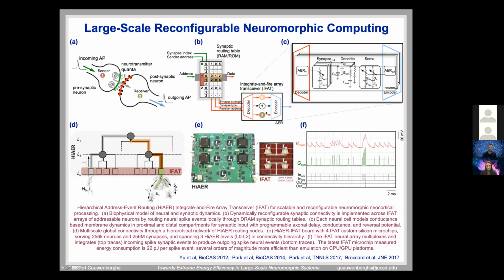So HiAER stands for this hierarchical organization, where we have a tree of nodes in the network where we just do message passing from one level to the next level. And so you only communicate source addresses rather than sending all the events, right? At the leaf node architecture, you have those efficient processors that actually do the computation, synapses and neurons, etc. Then you have local memory that couples to implementing the actual connectivity in the network.